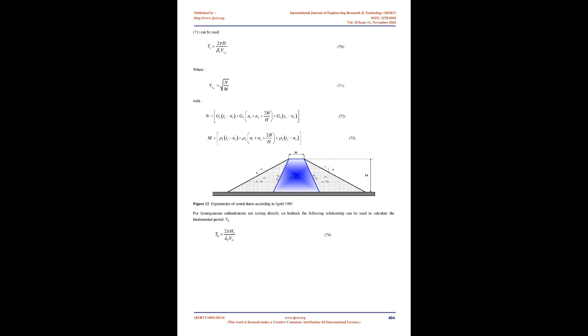4.2.2 Dynamic shear strength of the embankment. The dynamic shear strength of the embankment soil, obtained from triaxial tests, is determined not only by the evolution of the stress deviator as a function of the number of cycles, but also by the variations of the shear modulus and damping as a function of cyclic deformation or distortion.